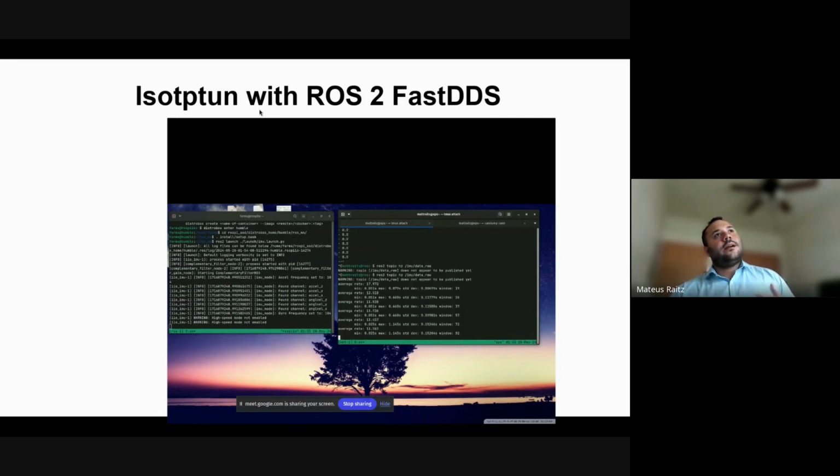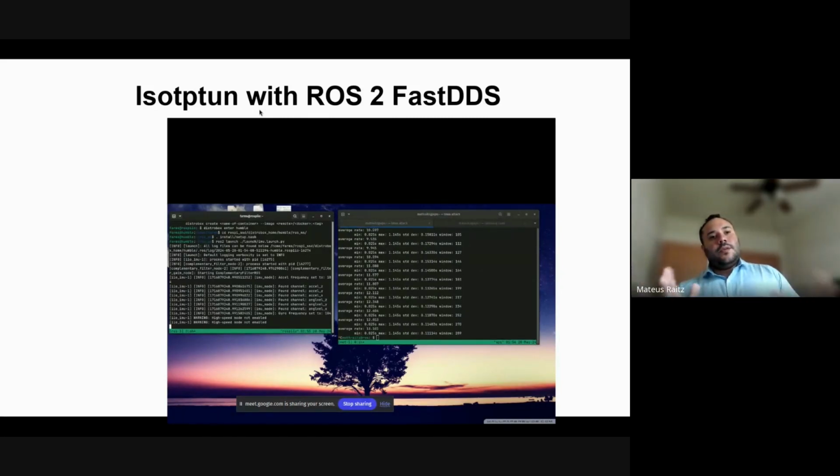And to do more tests in CAN using micro-ROS with CAN FD, because there are a lot of tests that I would like to do, but I didn't have the time because of all of the work I have to do in this project. The micro-ROS is just one part; the computer vision takes a lot of my time as well. Something I wanted to try and didn't is having multiple micro-ROS clients on the same CAN network and seeing how the agent works in that case, because the beauty of CAN is also having multiple devices on one network to simplify wiring.